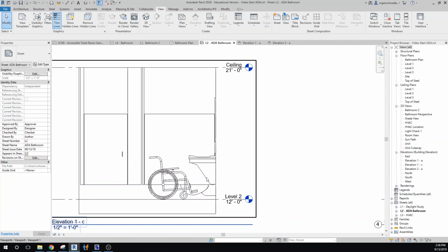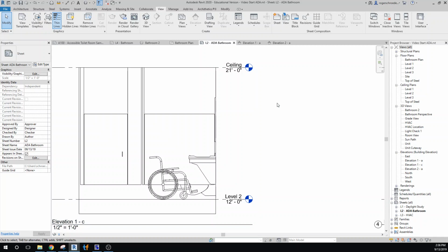The other thing about ADA sinks is this protection from burning of the hot water that would come down. One of the things that is an issue there is that many people who are paralyzed no longer have sensitivity in their legs. They can't feel them, so they can't feel the sensation of heat and cold. So they could easily be burnt by resting their leg on plumbing systems.